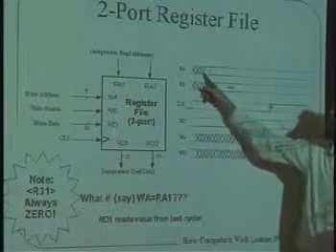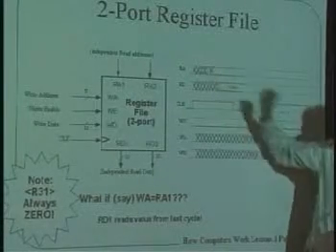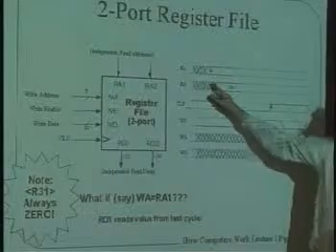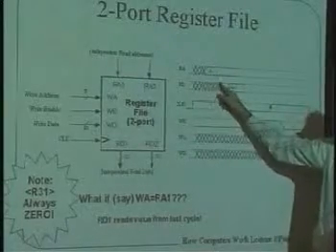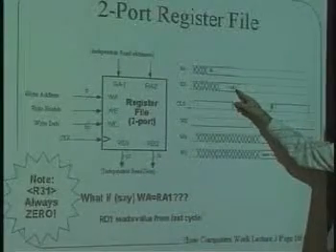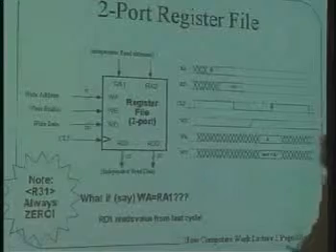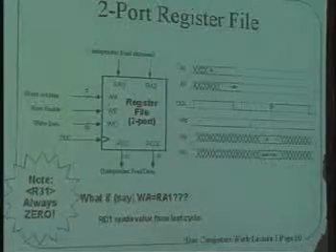A short time after it goes from having something that we don't know to settling down to having an address A, the register does its work, and after a short time the data comes out of RD, and that is the contents of A. And that's what a read of that register means.